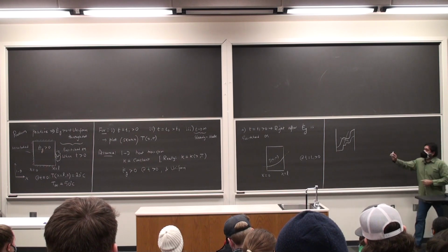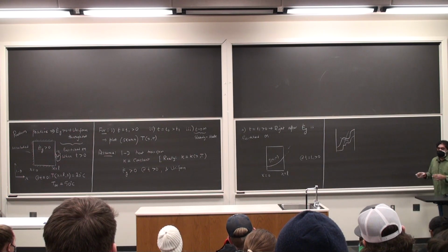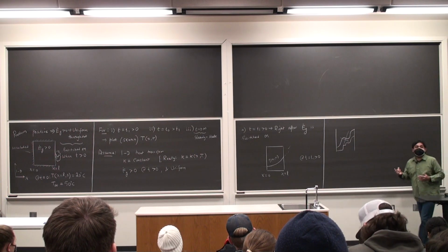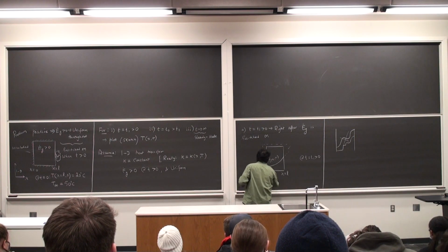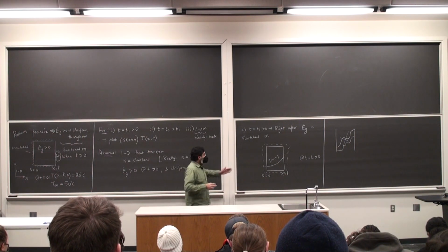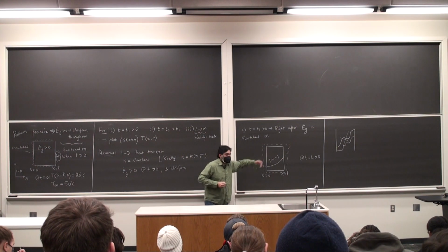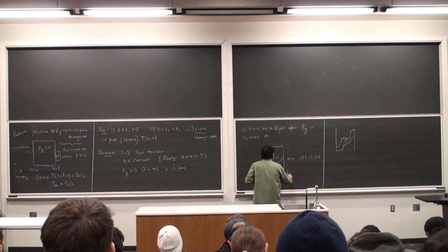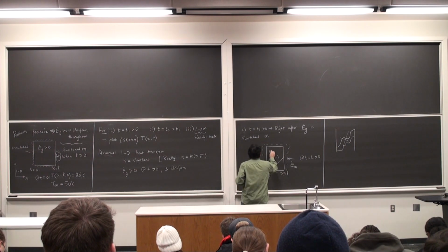Alright, so this is the temperature profile for us at time t equal to T1. You can obviously see if you perform an energy balance, if I draw a control surface around the entire wall, this side is insulated, so there is no heat transfer going in or coming out. From the other side, I have heat transfer coming in, so energy transferred in the form of heat. I have positive energy generation taking place, E dot G is greater than 0.